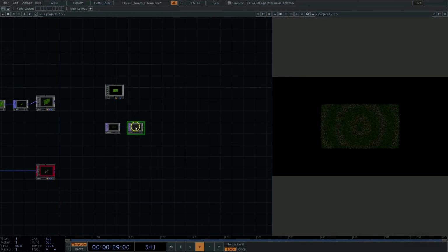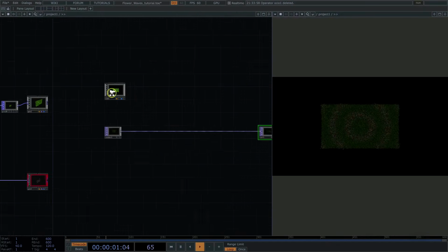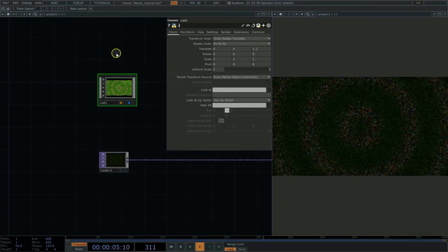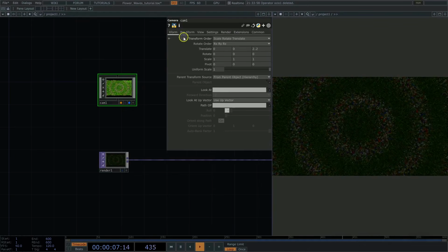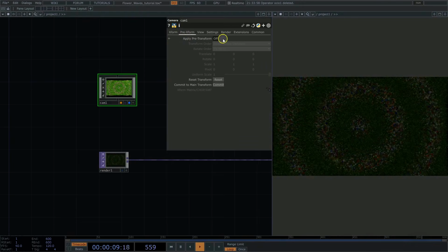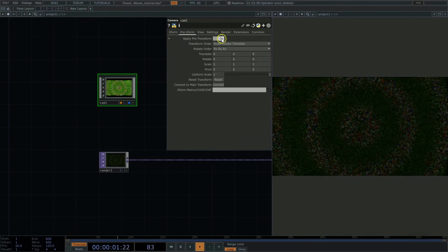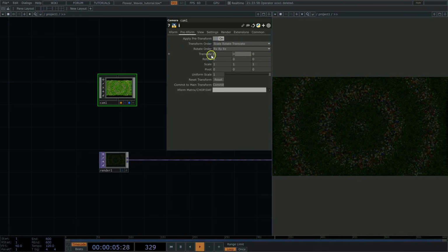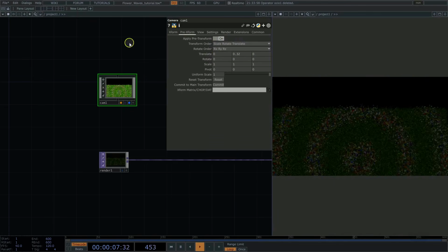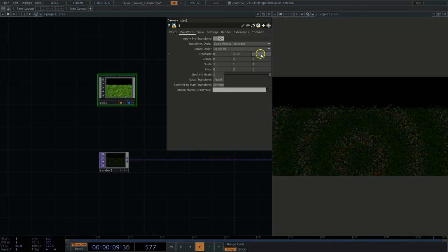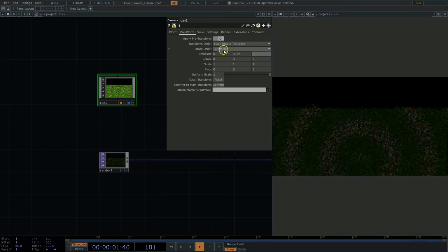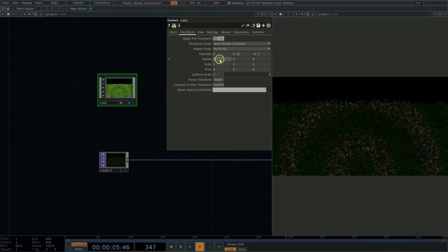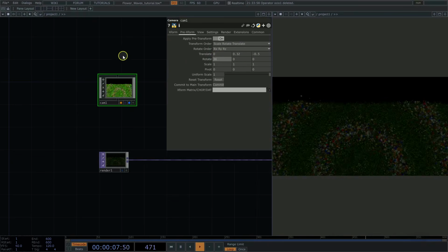On the camera, set Translate Z to 2.2. Go to the pre-transform page, toggle Apply Pre-Transform on. Set Translate Y to 0.32. Translate Z to -0.5. Rotate X to 36. This aligns the grass grid nicely. Tweak it to your taste.